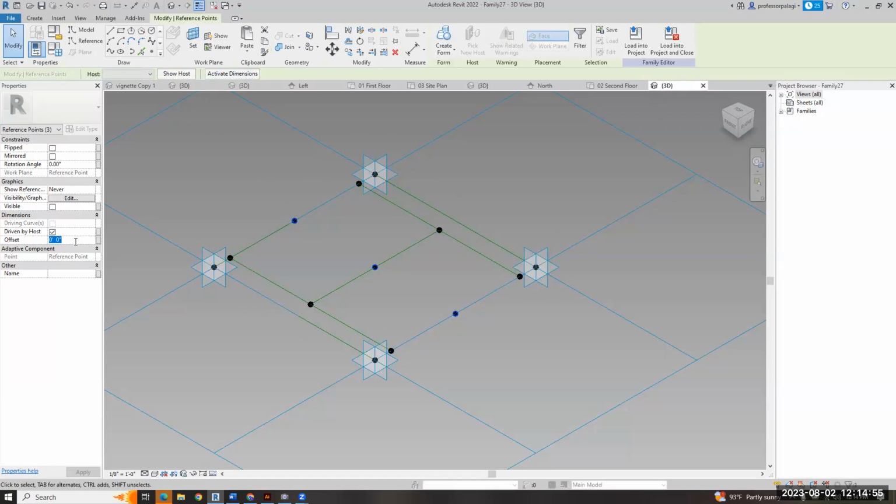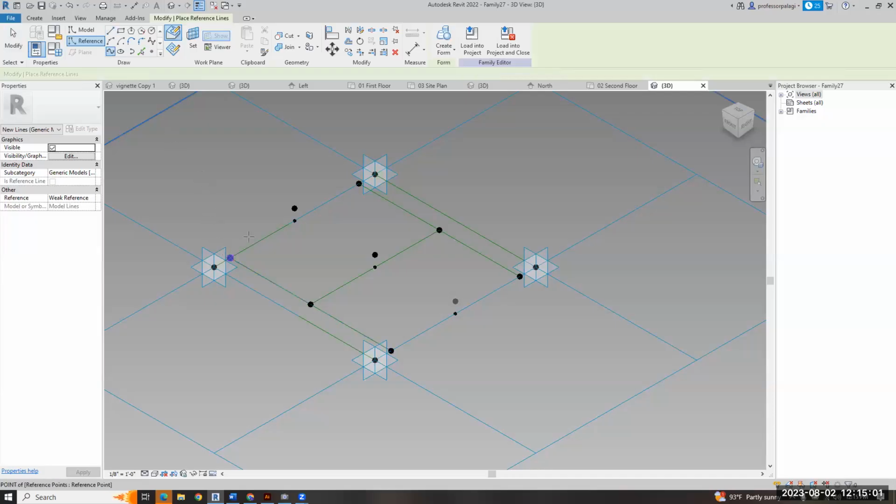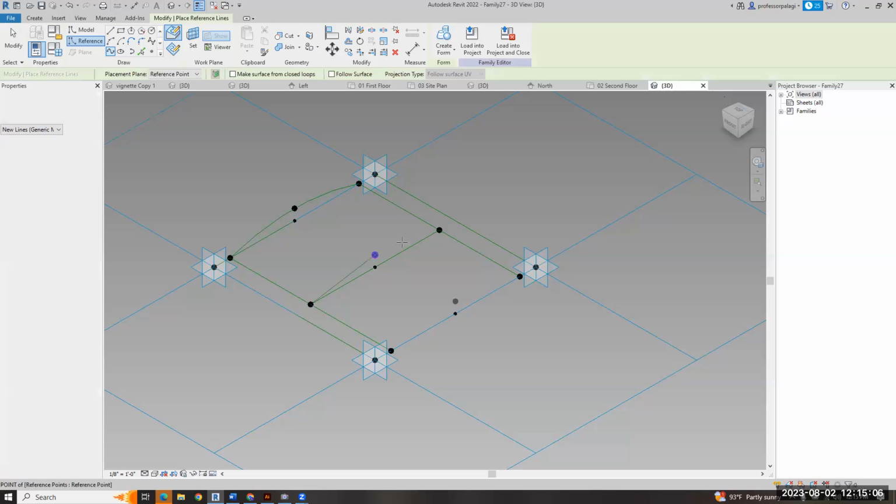And we put this up. Let's even do a little less. Let's say it's 8 inches up. Okay. Reference spline through points. Remember, it's important to always go the same direction. It'll get really upset if you don't go the same direction. So it thinks you're trying to fold it on itself.